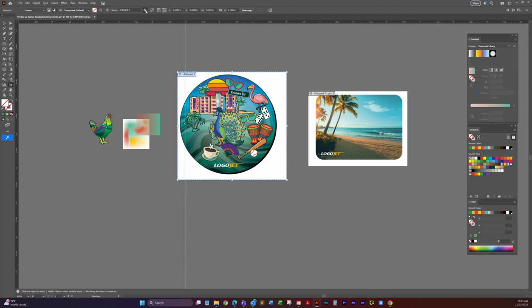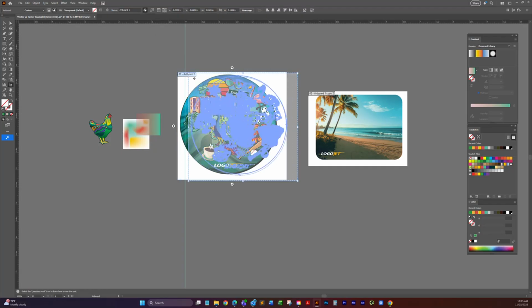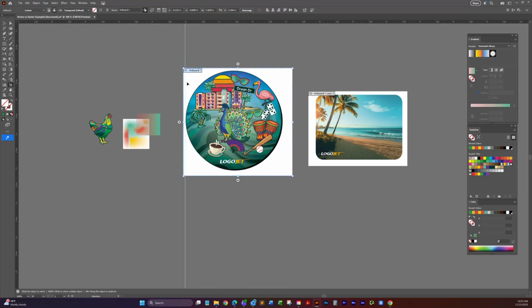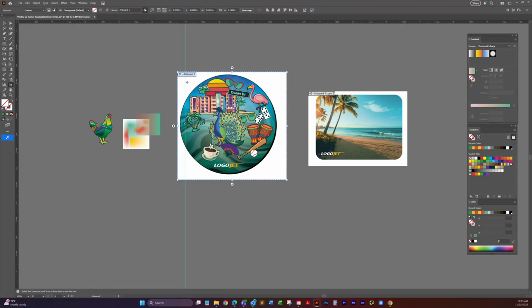You can adjust that. One important thing about the artboard tool is this little guy right here. This move and copy artwork with artboard. You can uncheck that if you need to move the artboard and have your art stay the same, or you can select it and your art will move with the board. There are some instances, I can't say which one you would prefer, but just know that if you need to move something around, this tool will allow you to either lock that art with the board or not. And there are some applications you'll discover that that's very handy.